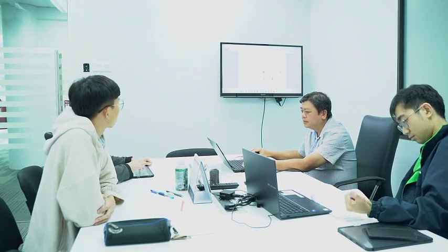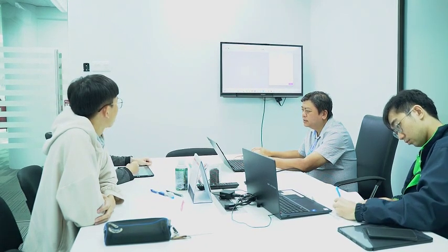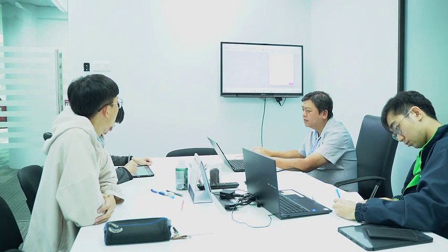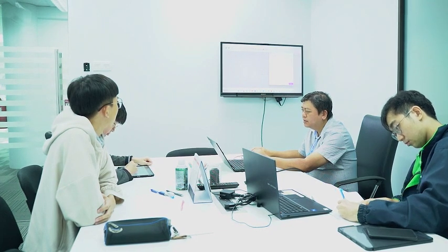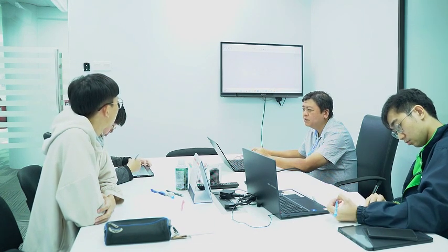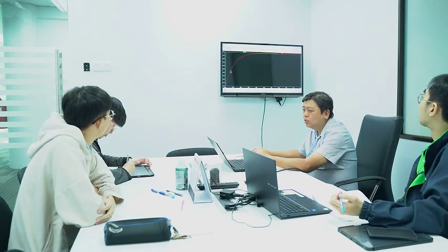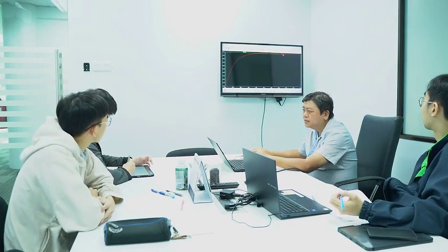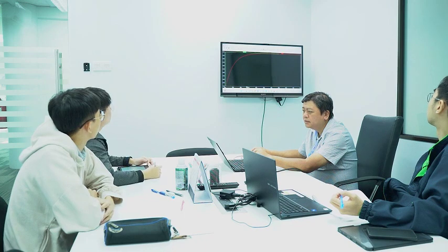1K and 1 micro, right? Okay, 1K. So you go to the calculator here. We work out RC: 1 kilo ohm times 1 micro, about 1 millisecond, right? As one RC constant, about 1 millisecond. Look at the curve here. What happened to the signal at 1 millisecond?